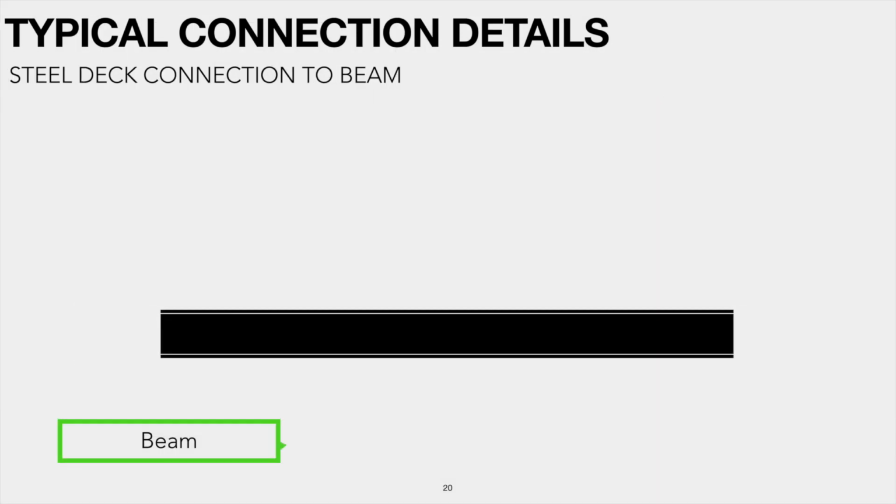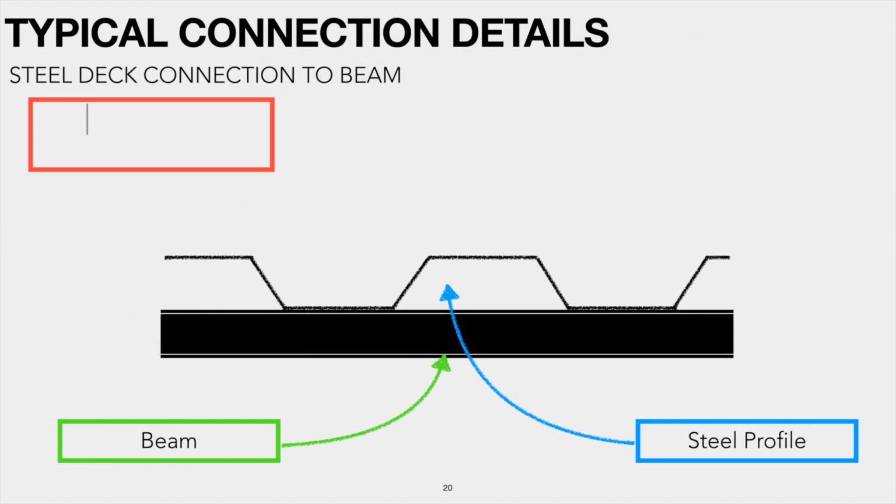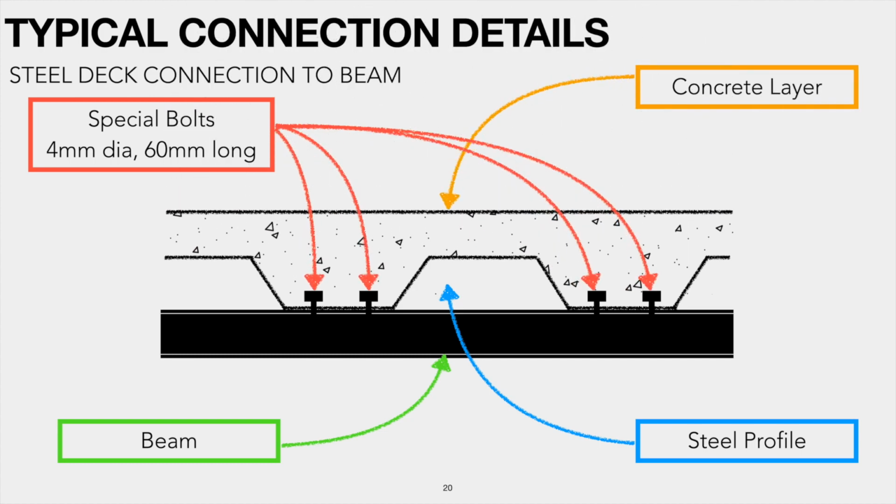Construction of steel profile deck with reinforced concrete bed is another work attached to this exercise. The steel profile deck is attached to beams by using special bolts. A count of 15 special bolts per square meter will be taken as an assumption for this exercise. In a real situation, you need to calculate the actual amount of special bolts based on the drawings and specifications for the project. Hereafter we are moving to the latter part of the session, named taking off measurement.